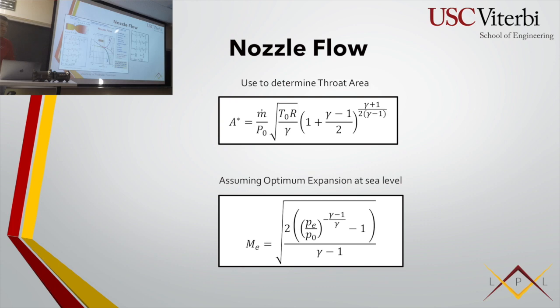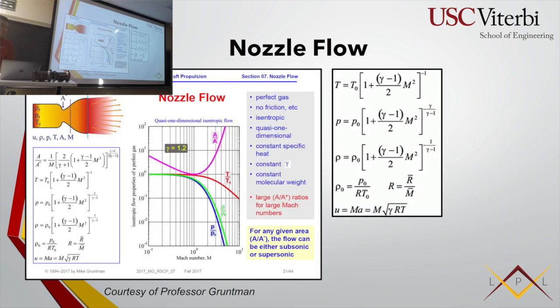Because when you add a throat, I think once you pass that, it's supersonic. So in subsonic... okay, yeah, I forgot. This is the whole converging, diverging nozzle, which I assumed everyone knew. So what David's mentioning is the way your rocket engines work: you assume the Mach number here is pretty much 0, right? And the way converging, diverging nozzles work is they use flow. If you accelerate it to Mach equals 1, and then all of a sudden you have an area that's increasing, the flow actually goes faster.